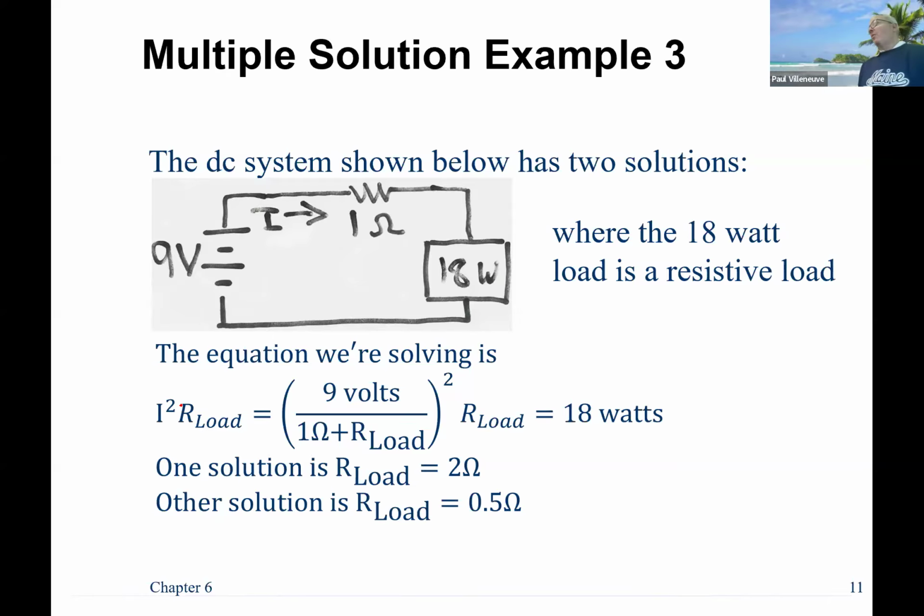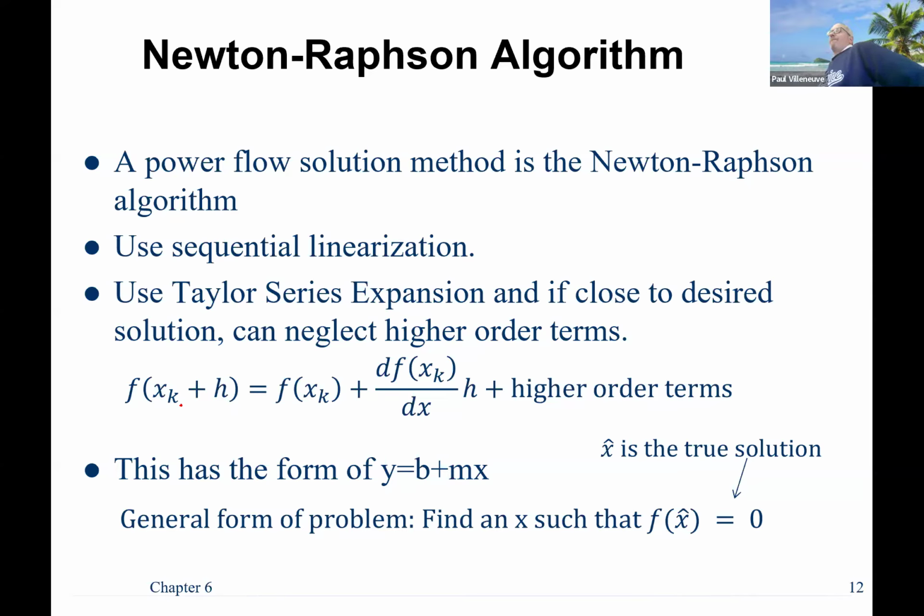So when you're doing a load flow, you have to do iterations. And you remember at the beginning of the semester, I said it would benefit you to use MATLAB. Why do you think I said that? Yeah, you can set up while loops in MATLAB, right? You can do very simple coding. You can do a while loop or a for loop. I use while loops personally, but you can set up a while loop to keep doing something until you get the result you want. Whereas in your calculator, I don't think any of your calculators can do while loops. Maybe I'm wrong, but I don't think you can. So that is the huge reason why I really suggest MATLAB, because of that iterative process with the sequential linearization.